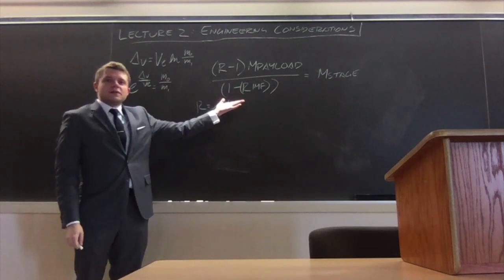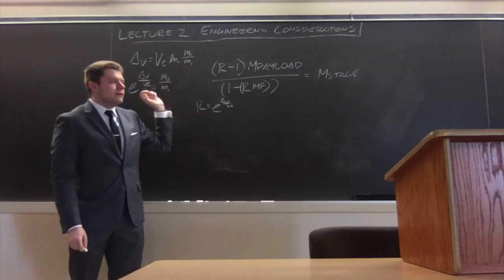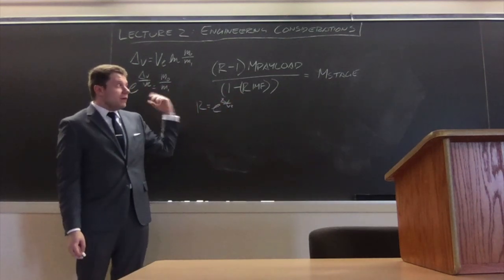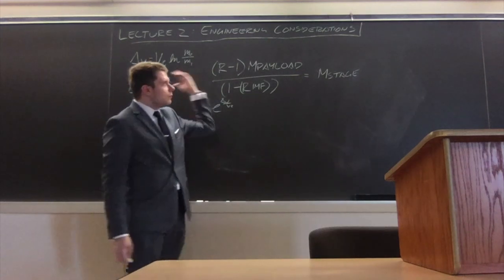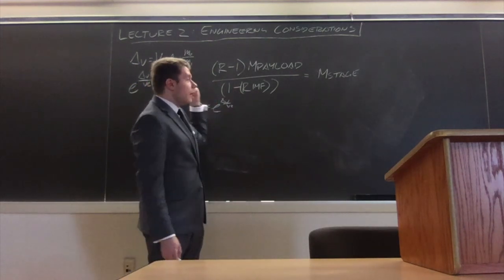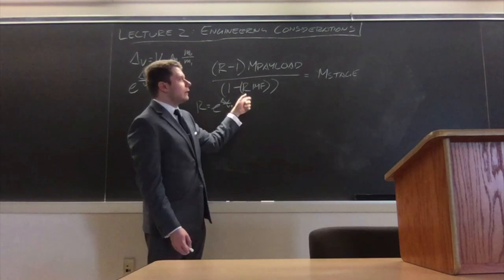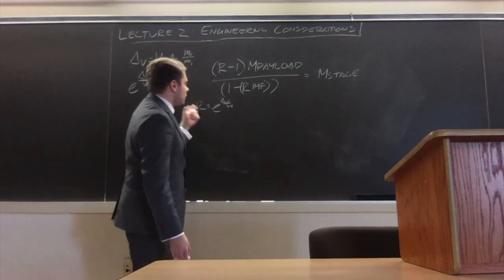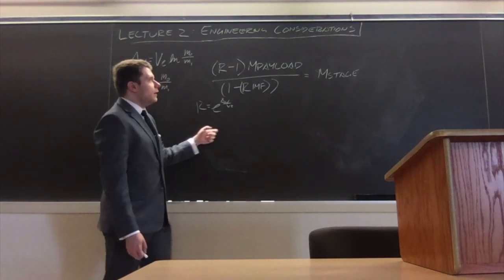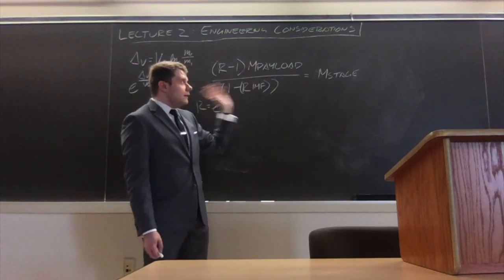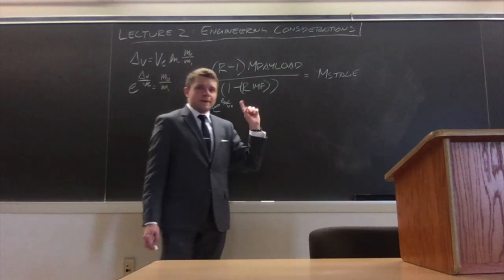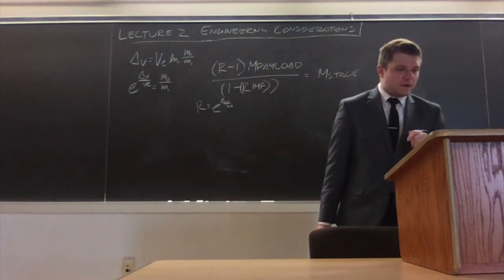This simple definition is really the starting point for trying to design basically almost any launch vehicle. Knowing from previous research what the inert mass fraction of your stage is probably going to look like, knowing your target delta V and your effective exhaust velocity, knowing how much payload you need, you can immediately take this and you can start doing things with it. And that is really, really powerful.